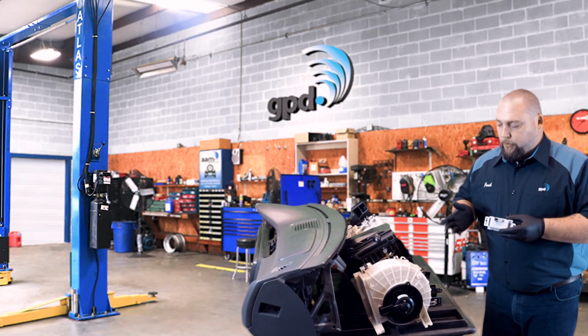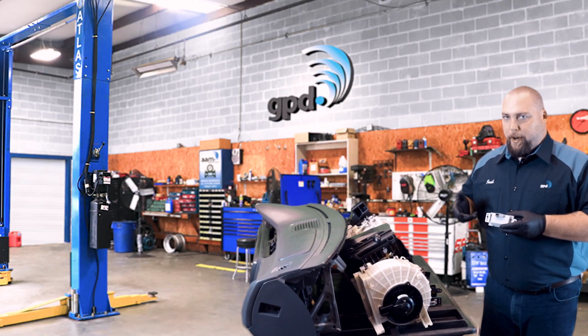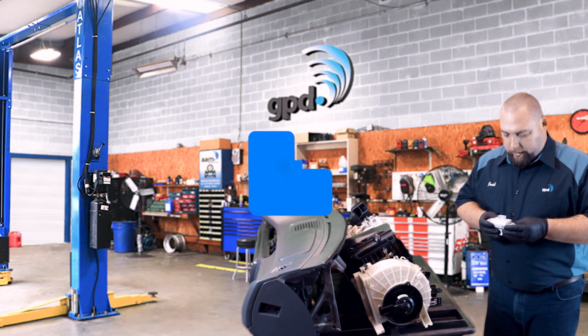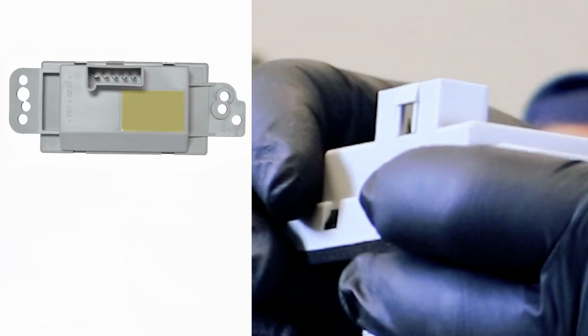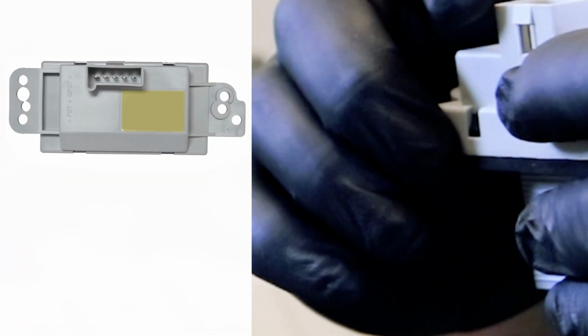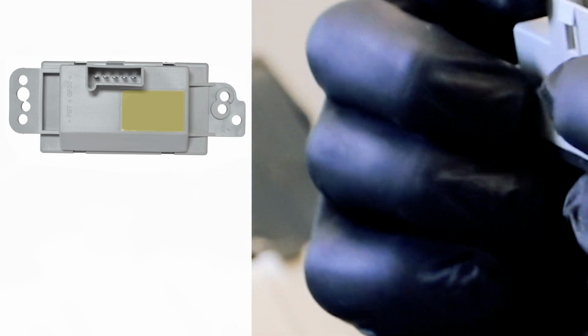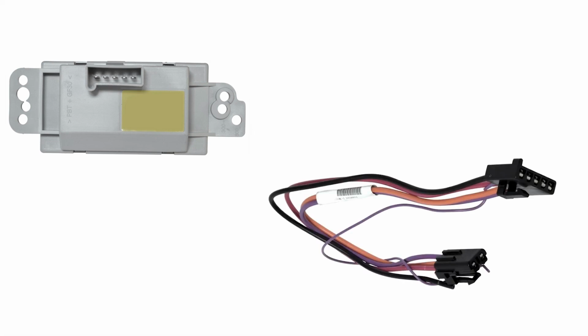If you hear noise coming from your blower motor, most of the time it has bearings inside that are breaking down. They can cause more resistance. It can actually burn up your module or your resistor. Always check the pins inside. Give it a quick look. Make sure you don't have any burnt spots, any melting plastic, anything like that, loose pins. If you do, then you're going to need to change your harness.